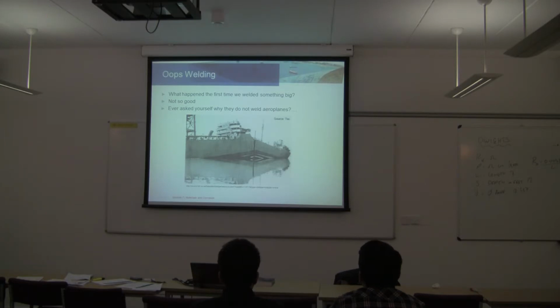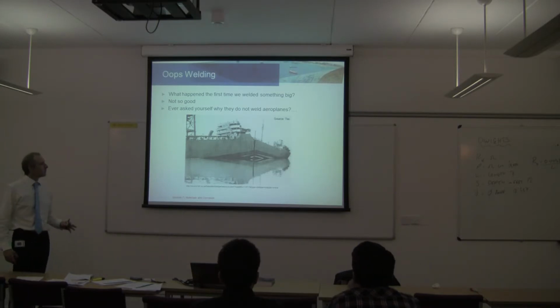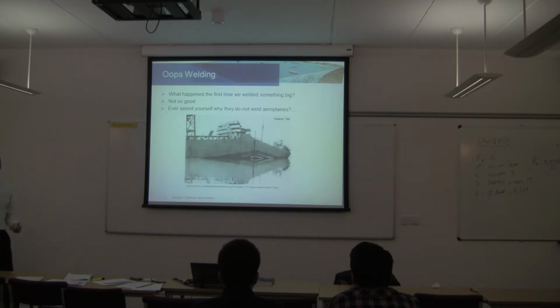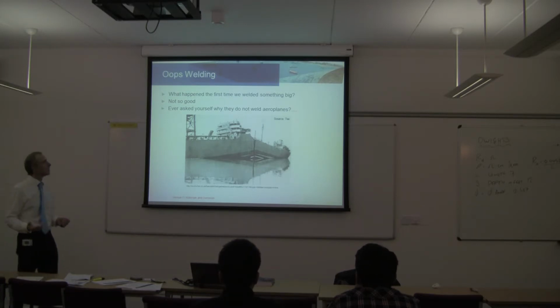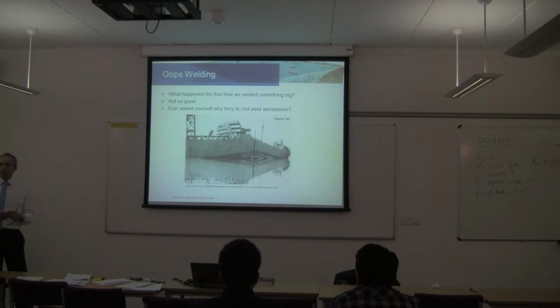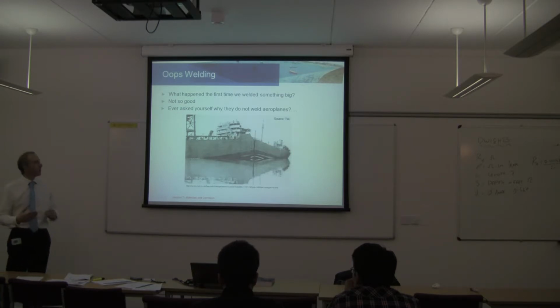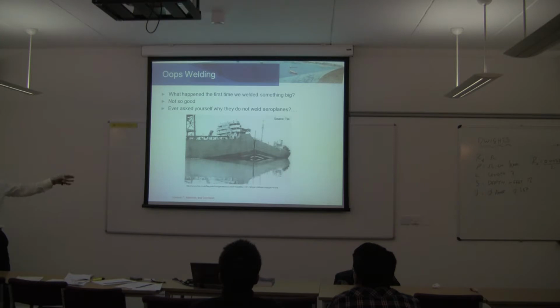Welding, going back to the early days, didn't really take off for construction, because back then they used to rivet metal together instead of welding, and they also didn't know much about fracture mechanics and what effect a weld would have on the metal. If metal is riveted together, crack propagation won't go very far, because as soon as it reaches the space where the metal is riveted together, the crack will stop. If your metal is welded together, the crack will just keep on going.